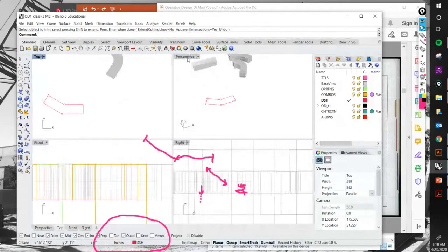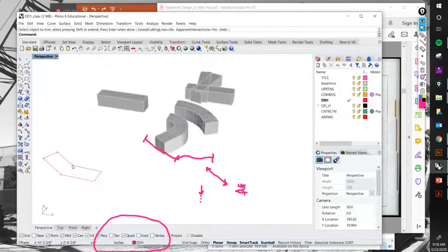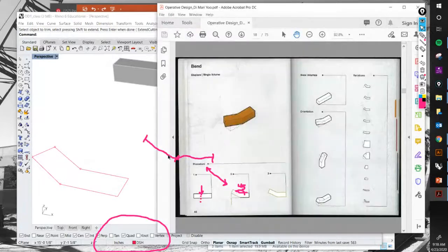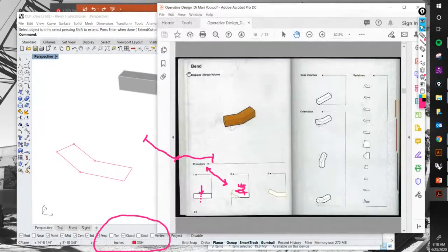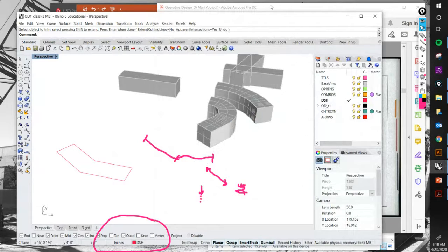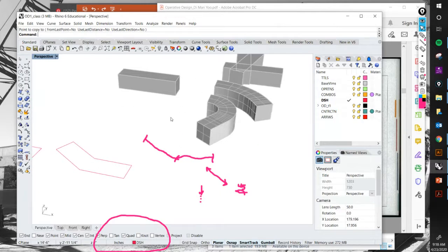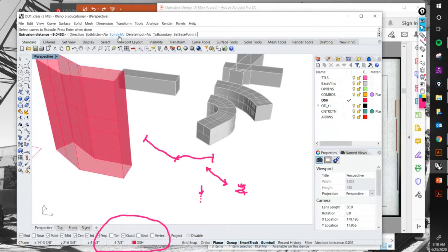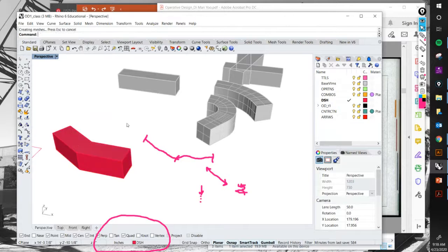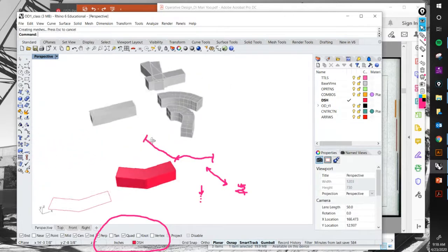Now if we go into our 3D view, you can then observe that, and from there, very, very simple, we can extrude. Well, actually, let me go ahead and copy this curve so that we keep it for our records, keep the receipt. So we can then extrude curve. And I'll do that. Make sure that I set solid to yes, and I extend that there.